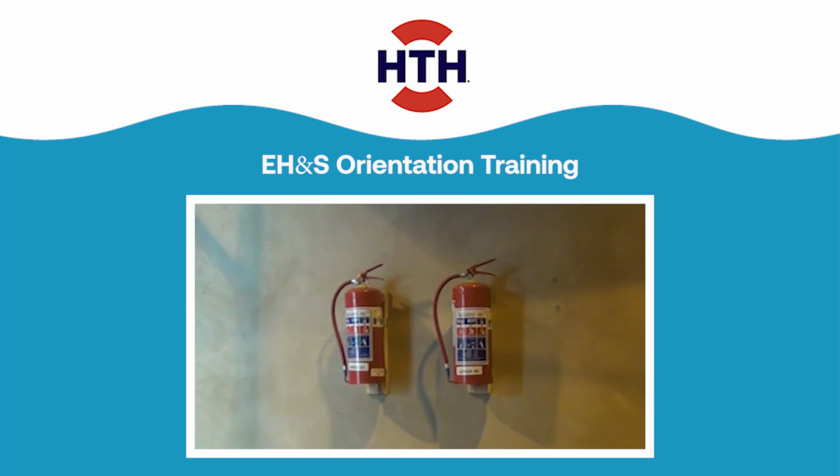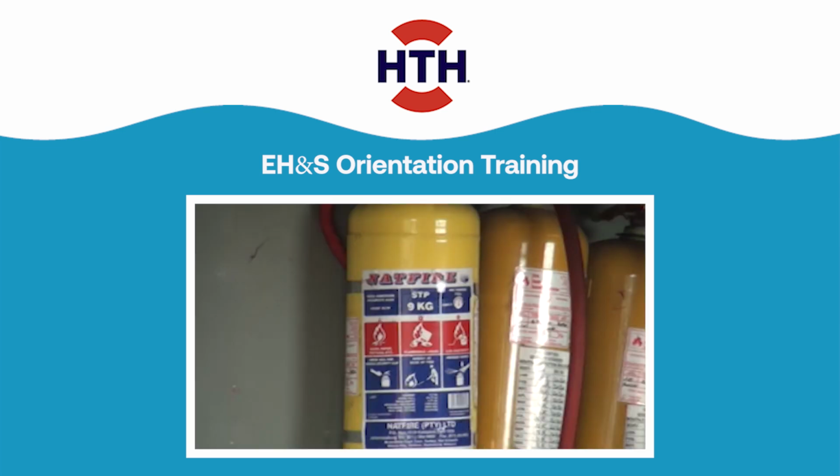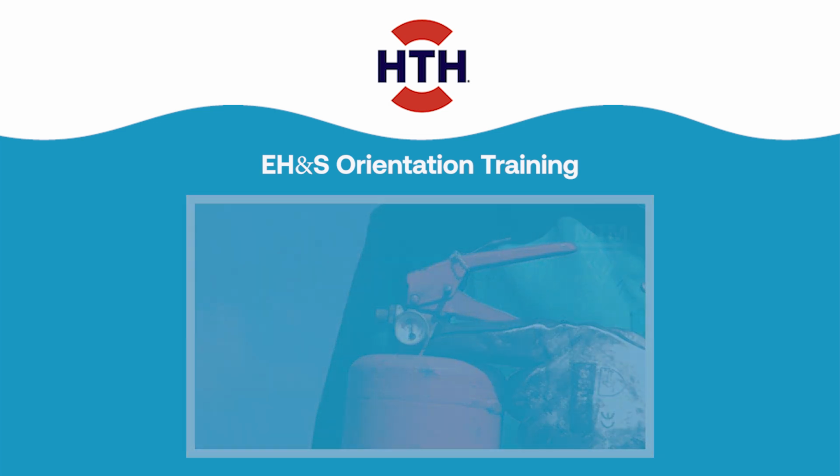For most extinguishers, this is a job that you can easily do by locating the extinguisher in your workplace and answering the 3 questions below. Is the extinguisher in the correct location? Is it visible and accessible? Does the gauge or pressure indicator show the correct pressure?